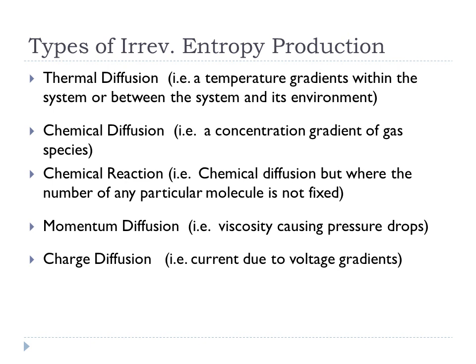But guess what? Things like diffusing against gradients. So what's happening is you have species diffusing against that velocity gradient, and as it's doing that, it's causing irreversibilities, which you need to overcome through pressure drops. Okay, the last one here, which we won't cover much in this course, as opposed to a course where we're looking at fuel cells, is charge diffusion. That is diffusion of charged species across gradients, either in voltage and/or in concentration.